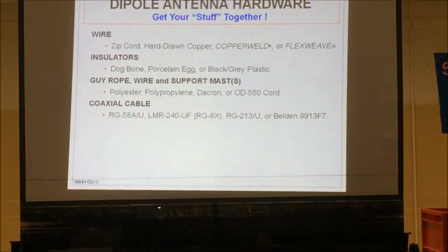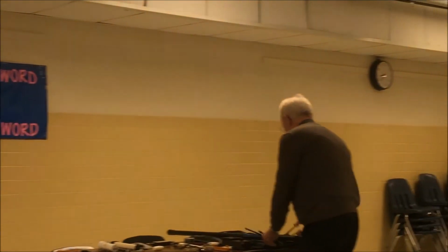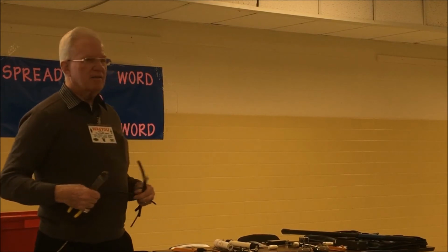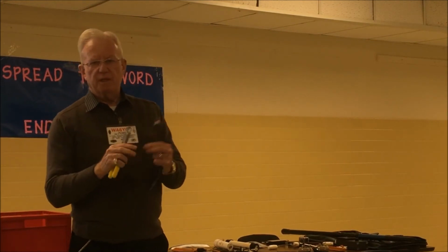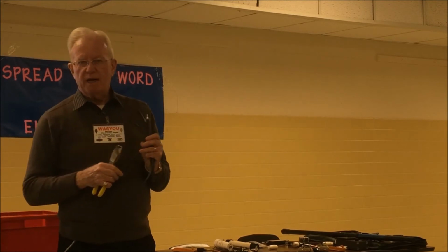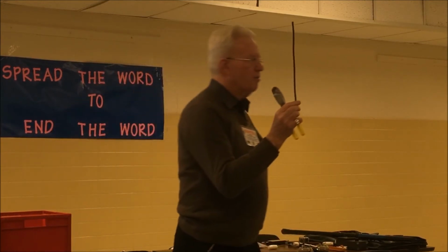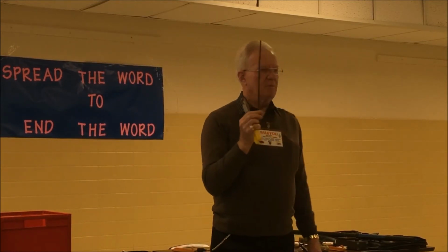Coax, guys, as you know, you've probably attended one of my briefings before. I could talk about coax all day. So let's get into this a little more. What's the most popular coax in here you guys like to feed your antennas with? 58? 213? 8X. Boy, 8X is catching on, isn't it, Mike? Everybody's using that stuff. Now, Mike called it 8X. I wouldn't think of calling it 8X because I don't want you to go out to eBay and buy some cheap crap. Don't go buy 8X. If you're gonna buy it, go buy some LMR 240 or LMR 400.